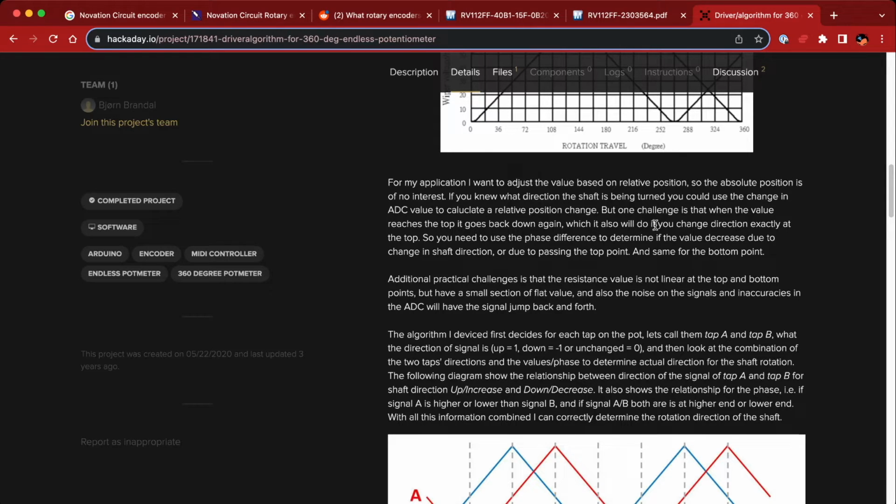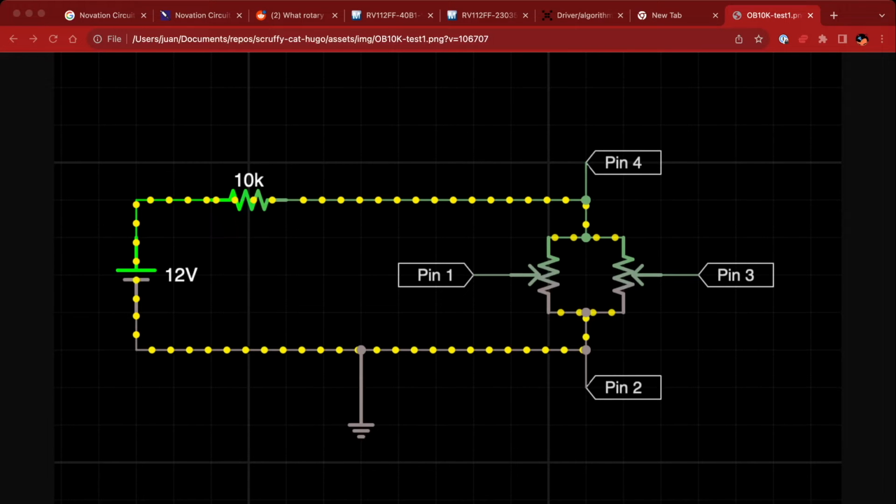readings. Okay, for this first part of the experiment, this is what we're going to hook up. We have a power source connected on the positive rail, so 12 volts goes into a 10K resistor. I chose the value of 10K because the potentiometer I have is also 10K, and so I figured it would be easy for us to get some values out of this.